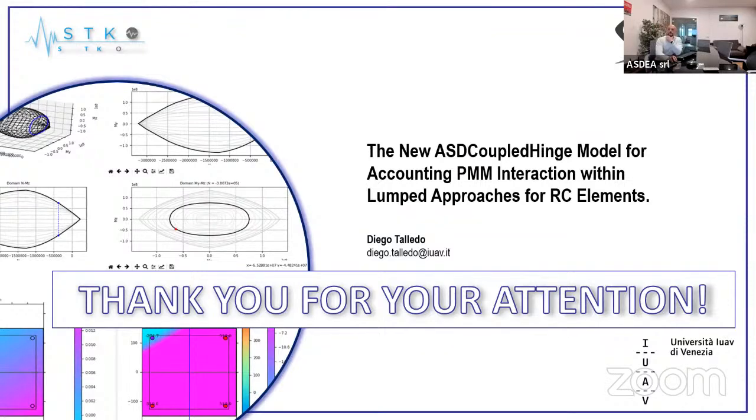Yes. So, okay, if there are no questions, or at least no question right now, I would like to thank you everyone again, and there will be other webinars. The next one will be in May, and we are going to present some other new features that we added in OpenSees, in particular the new ASD shell T3, which is the triangular counterpart of the ASD shell Q4, based on the same formulation. Basically, it's a thick shell considering out-of-plane shear deformation.